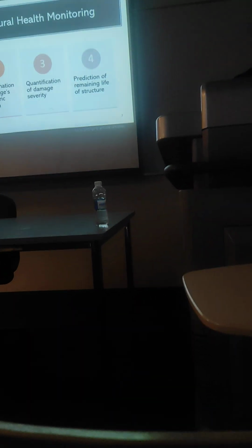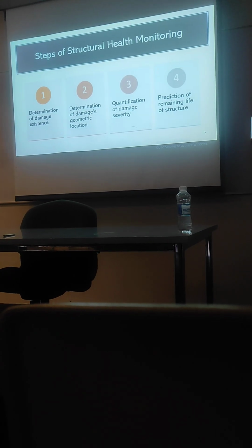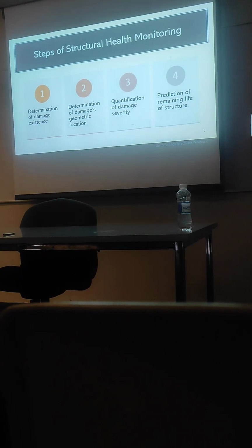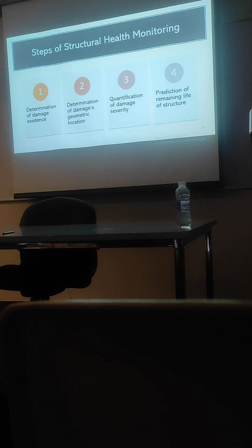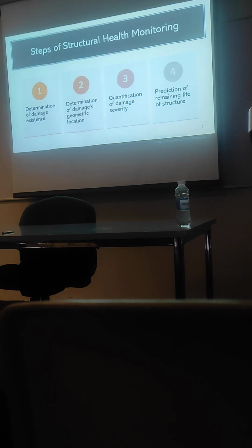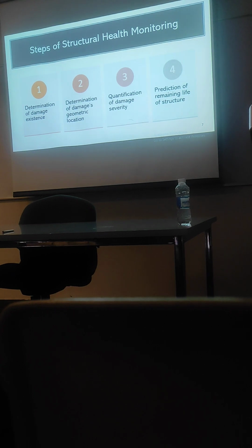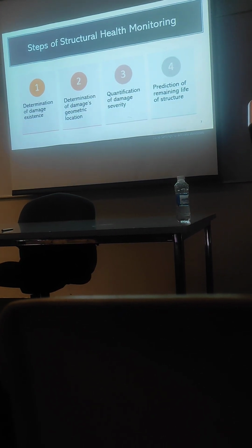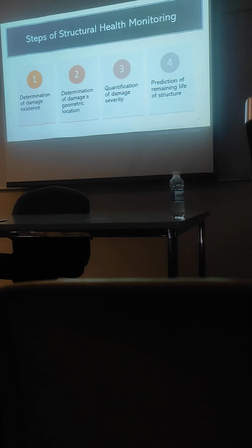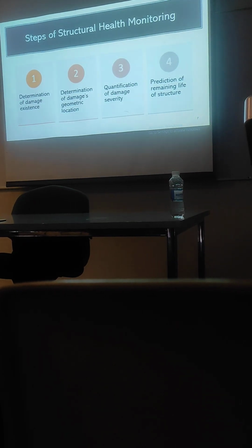And the third step would be quantification of damage severity. This will help us to implement the specific system that is required for any structural health monitoring. And lastly, the prediction of remaining life of the structure. Nowadays, this fourth step is one of the most important steps in structural health monitoring, because now we are trying to predict the trend of the structural behavior, or how the structure will behave under certain conditions.